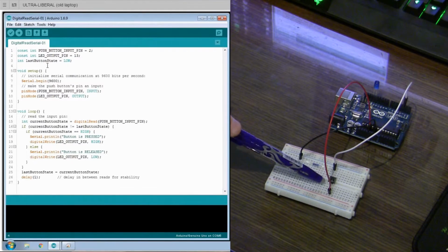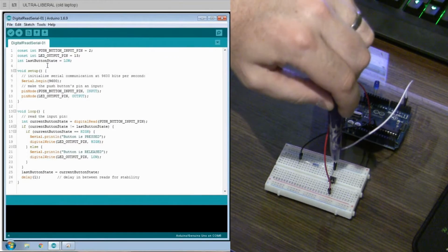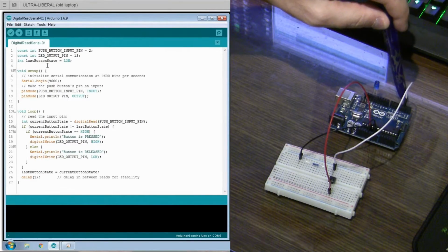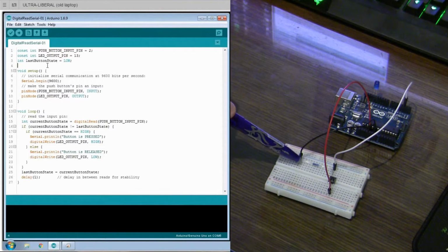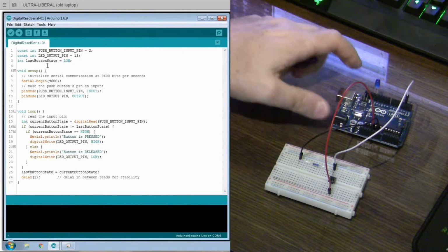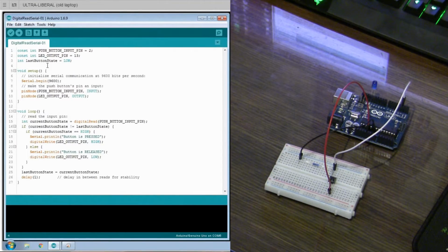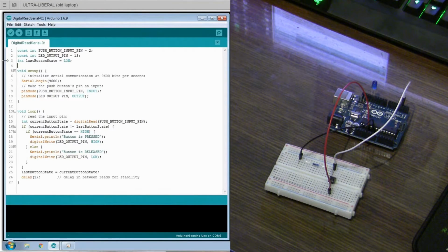If you push the button, it will close the circuit, and then we will get our flow going over to both the signal wire that's connected to D2, as well as the 10,000 ohm resistor, and then the black wire goes back to ground. So nothing new there. The only change is what's in the source code. So let's take a look at that right now.